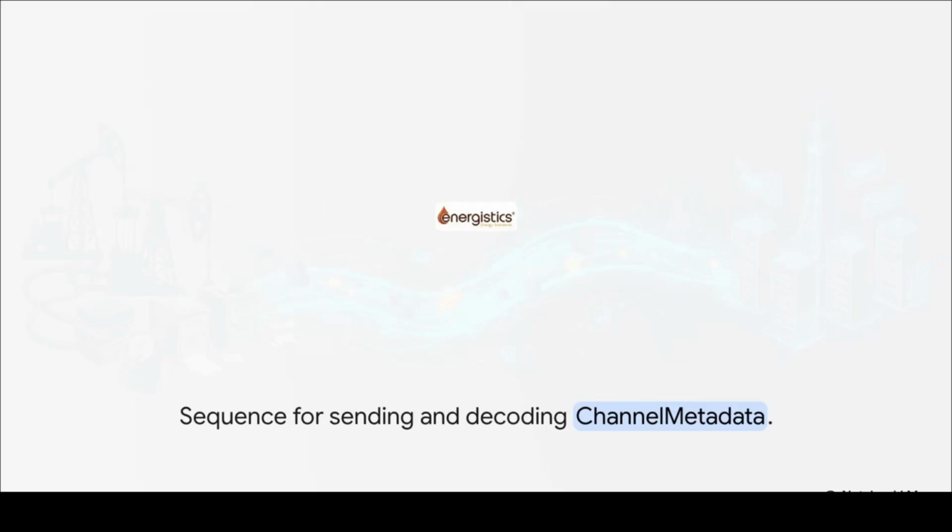But hold on, before raw data can just flow, the system needs some context. The producer sends channel metadata messages. The aggregator absolutely must decode this metadata because it contains the local identifiers for the channels. It takes that metadata and assigns the upcoming stream to the correct wellbore and log hierarchy. This decoding step is absolutely crucial. It must be completed before any actual log values can be received. If you skipped this, you'd literally just have random numbers with no idea what depth or tool they belong to.